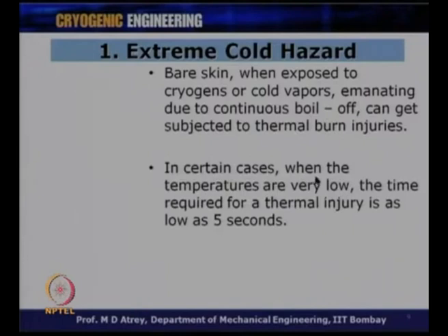In certain cases, when the temperatures are very low, the time required for a thermal injury is as low as 5 seconds. For example, if your body gets subjected to liquid nitrogen or liquid helium by some mistake, it can lead to thermal injury, and the damage could occur in as little as 5 seconds. So, you have to be very, very careful while handling such cryogens.